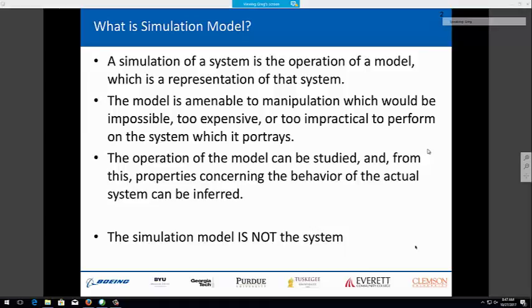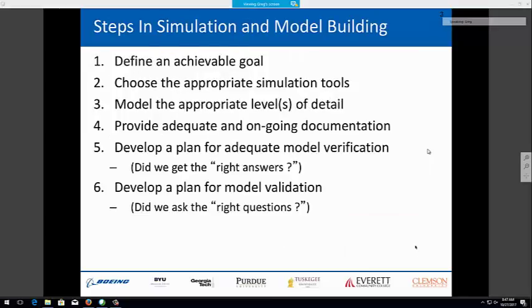But basically, in the finite element modeling process, we allow basically an auto mesher now to divide a solid continuum geometry into smaller and smaller elements. Each of those is called an element. They create a mesh. Those elements have nodes and edges associated with them. And each of those elements in step B is assigned some sort of governing model. Okay? So that governing model is going to be contingent on what sort of behavior we're looking for.